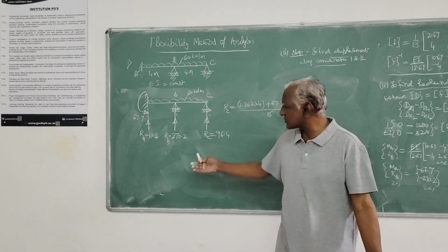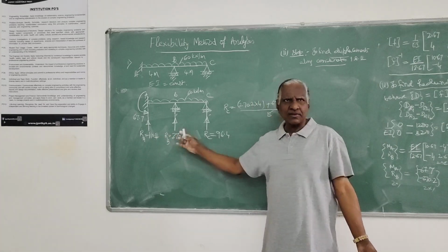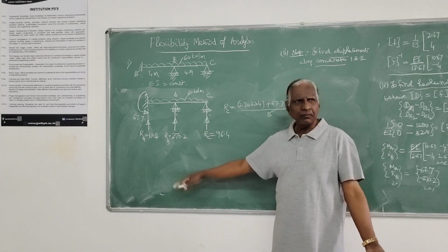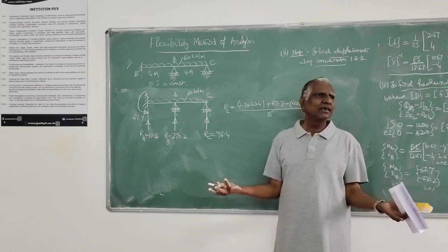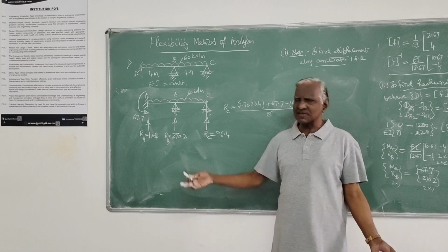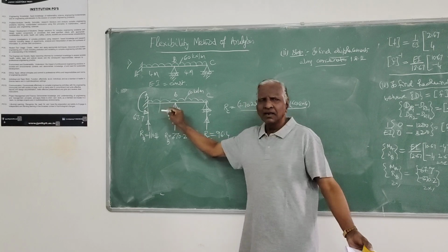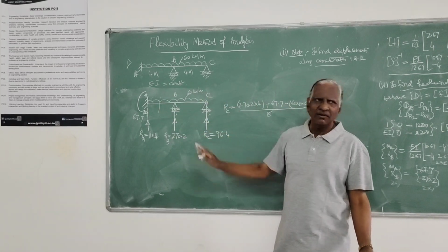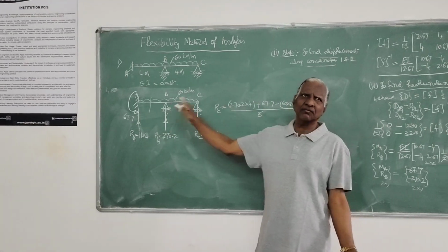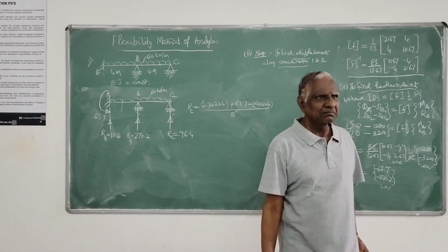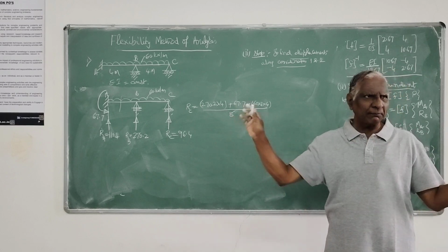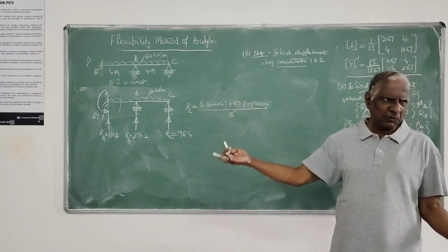You can do it, because the moment you know all the support reactions, since they are the only unknowns, plotting the bending moment diagram and shear force diagram is very easy. There is nothing to it: you take some section, find Vx and Mx in that section, and plot it. One from the left hand, another from the right. It's a general bending moment diagram, and you need not superpose the free moment and V moment.